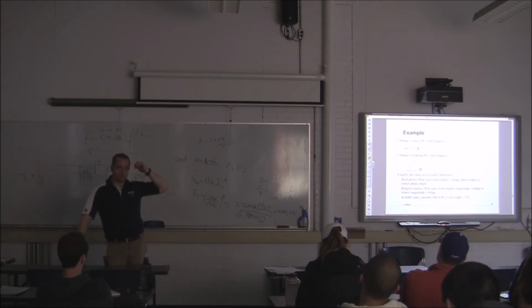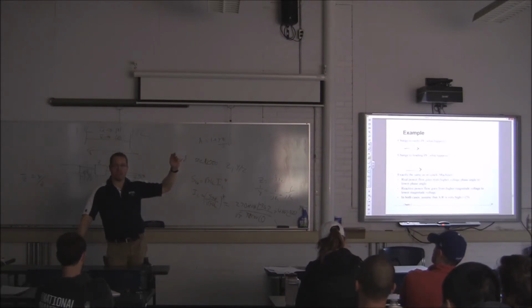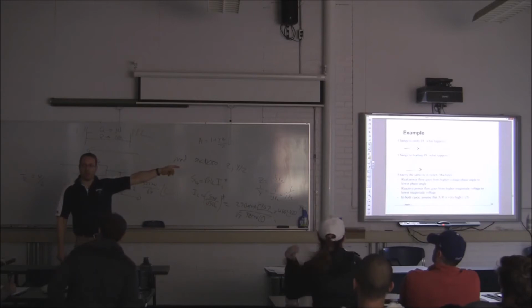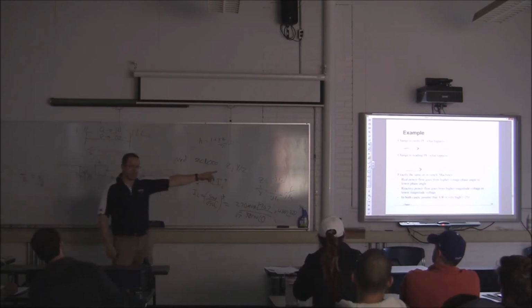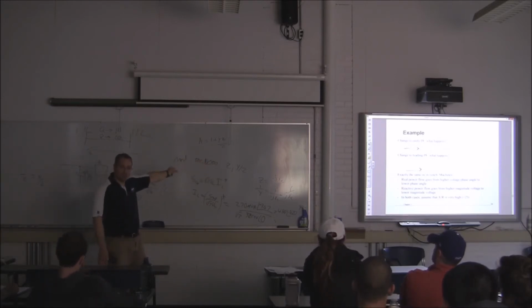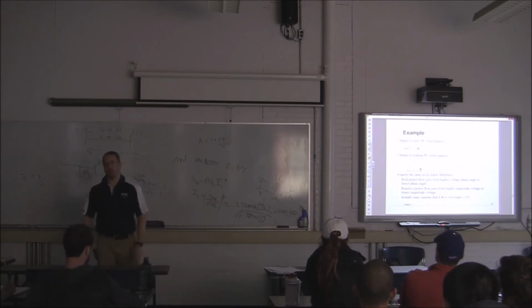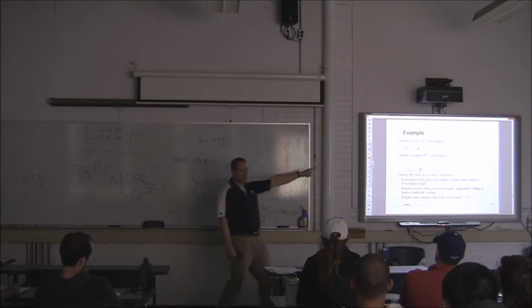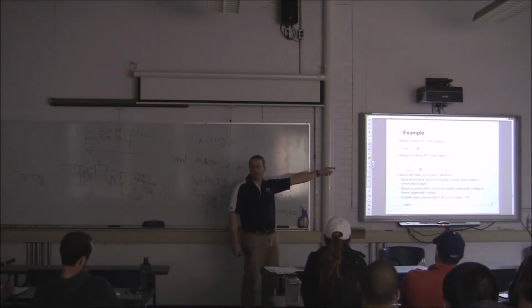Okay? Think about it in terms of a capacitor. What do you see in a capacitor first? Current or voltage? When you energize a capacitor, what do you see change? Current, and voltage doesn't change, right? So the idea is that there's current going to the load before the voltage builds up, so that current is starting to provide or discharge back to support the voltage. That's why you get that reactive power support. So your voltage magnitude, Vs, can be less than Vr in steady state.